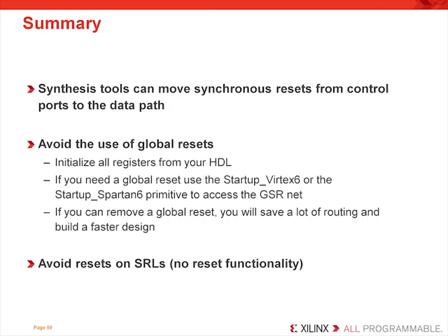If you need a global reset, use the startup block for either Virtex-6 or Spartan-6, and again, initialize that in your HDL. If you can remove a global reset, you will save a lot of routing, and this will give the tools more flexibility to meet all of your timing needs, often critical timing needs.